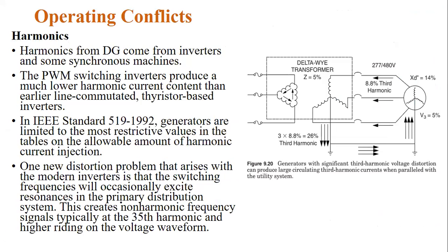The next topic is harmonics. Harmonics are very common in the power system, and increasing harmonics in the system may lead to more heat generation in any machinery or equipment, which may lead to damage of the insulation and damage of the equipment also. That's why harmonics are very important in the power system.